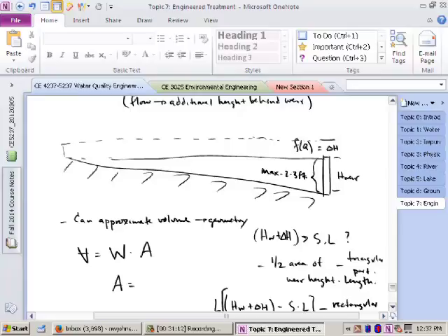What would be the only alternative in that situation? It's not going to work very well because there's length to width requirements as well, but you could make it a lot wider, right? But then there's the idea that if you put the flow in on one side, it's only going to go right down the middle. It's not going to spread out along the whole thing. So that's why the length to width should be at least 5 or 10 to 1.